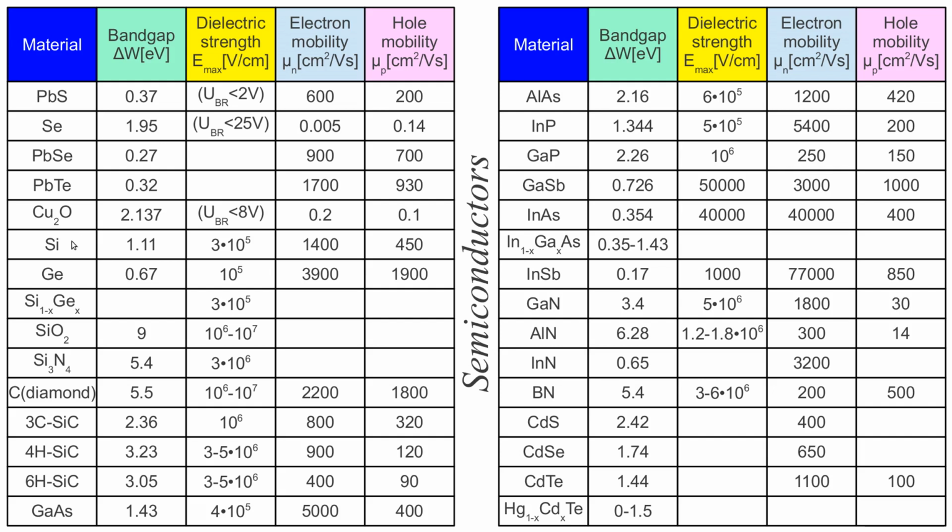Because silicon is an indirect band gap semiconductor, the likelihood to generate a phonon, a particle of thermal movement of the crystal lattice of silicon, is much more likely than creating a photon, a particle of light. On the other hand, the generation of photons is very efficient in gallium arsenide, gallium nitride, and other 3-5 components. So we need these components.